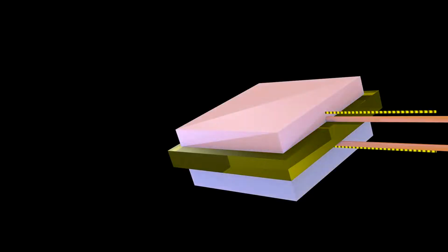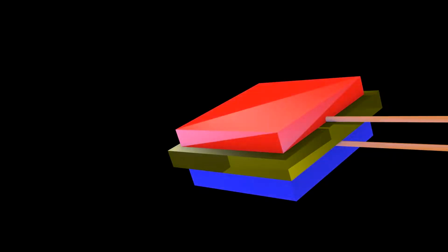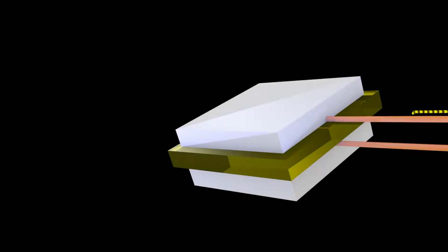An unchanging voltage charges the capacitor up to the voltage and then stops. Current flows while the capacitor is charging. A changing voltage charges and discharges the capacitor, so that current flows almost as if the capacitor weren't there.